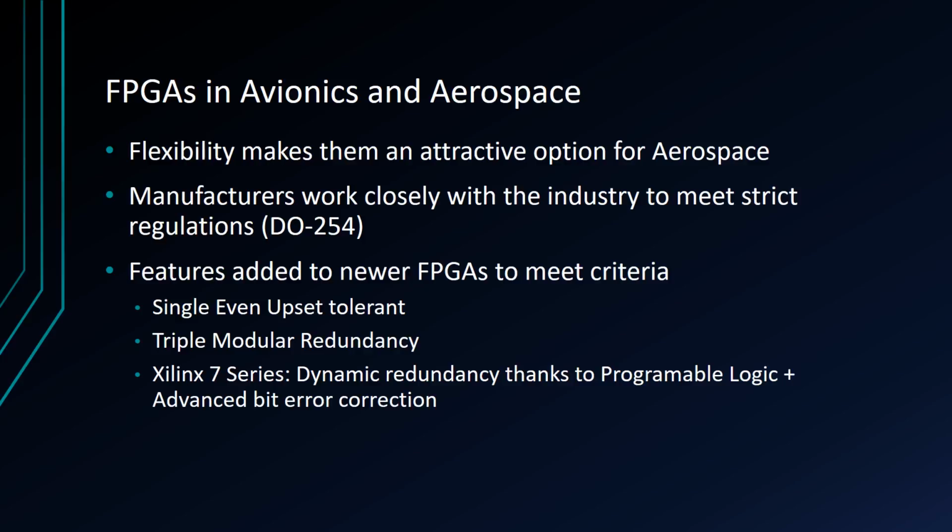One specific example I looked at was FPGAs in aerospace. Here I saw FPGA manufacturers working very closely with the aerospace industry to meet their strict regulations, such as DO-254, which I looked into. Features that have been added to meet these regulations include single event upset tolerance, triple modular redundancy, and Xilinx recently came out with their newest boards having dynamic redundancy, thanks to the FPGA's programmable logic and advanced bit error correction.